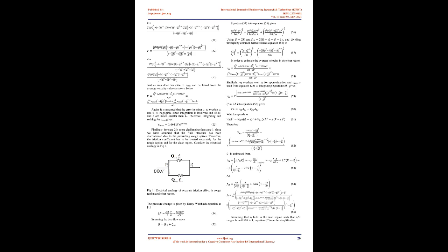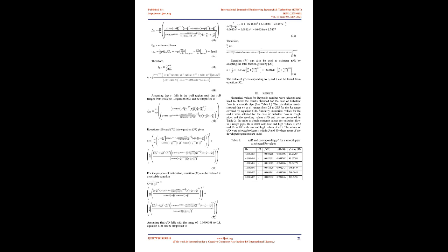Experimental investigators have reported that the wall/outer region boundary location is dependent on Reynolds number, but not as detailed as the result presented here. For turbulent flows in rough pipes, the results of the analysis shown in Table 2 show that the normalized distance from the wall at which the wall/outer region boundary exists is a function of the relative roughness of the pipe. In more detail, the normalized distance from the wall at which the wall/outer region boundary exists may increase or decrease depending on the combination of variation of the Reynolds number and relative roughness.